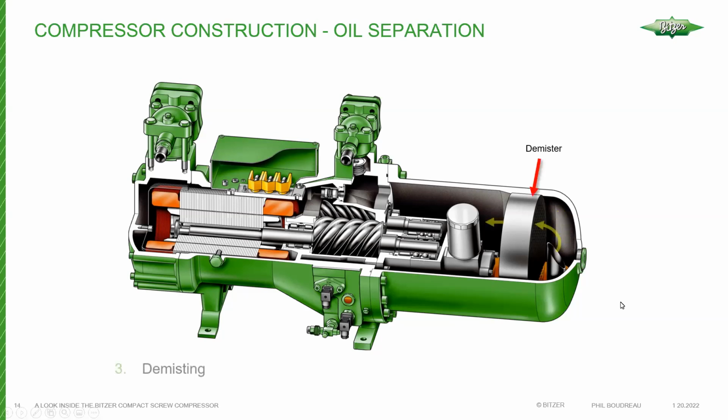And also there is a final stage, we'll call it demisting, which is basically another form of impingement, I guess you could say, but also allows for some coagulation of the oil as the droplets all collect together and drain down into the bottom here. You can see the light brown shaded area here indicates that this entire oil separator along to the sight glass has a good layer or level of oil in there.